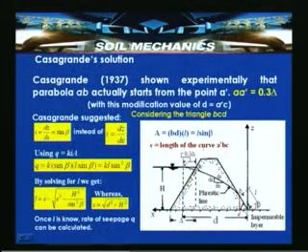where S is the length of the curve A dash BC. That is, from here A dash BC is the length of the curve S. This is the length of the curve A dash BC, which is represented by a small s here. So with 4 to 5% error, we can approximate S is equal to root over d square plus h square.